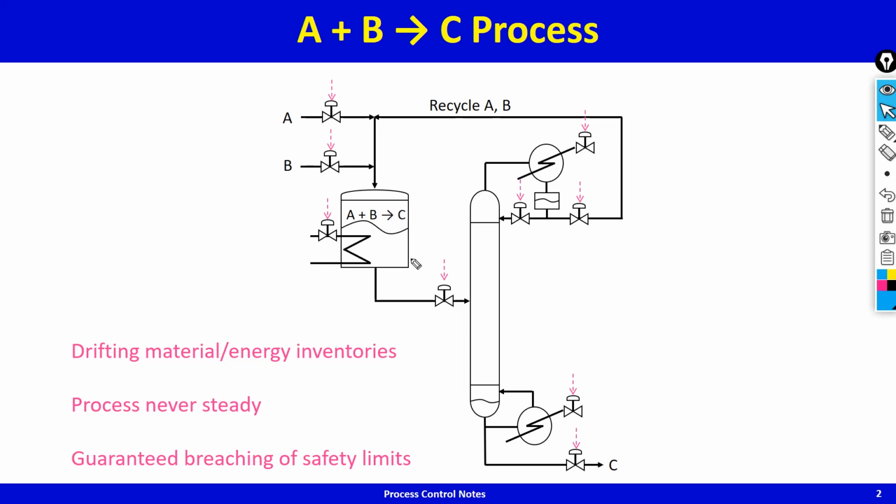So now you need a control system so that basic material and energy balances are closed robustly. And so we say, okay, let's do the minimum possible to close all possible independent balances. We're going to move these valves to close different balances.